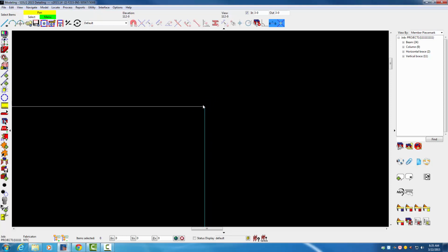If you have two beams coming to a point, SDS2 doesn't know which beam you want to frame into which beam. So if I want this beam here going horizontal on my screen to frame into this one going vertically, the vertical one has to go beyond. So again, if we look at your sheet S3 and look at elevation at grid line 2, this beam here is on grid line 2, you'll see that this beam here also should extend past 4 inches.